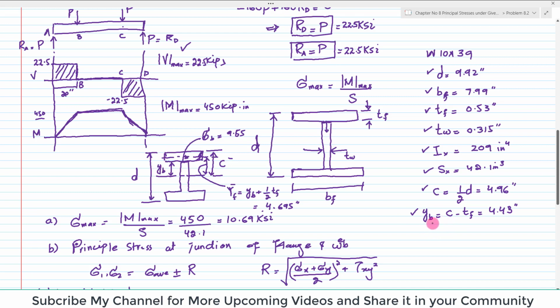Now you have the section modulus from here and you have bending moment from here, so you can put the value in here. Bending moment is 450, section modulus 42.5, which will give you 10.69. Again, this is the maximum stress at the outside of the flange.